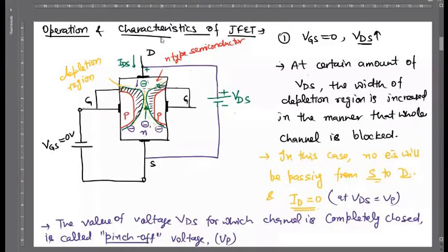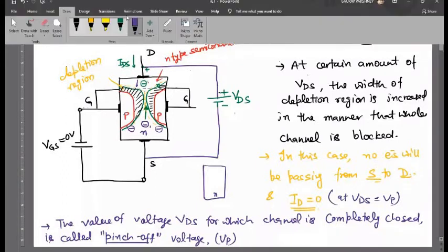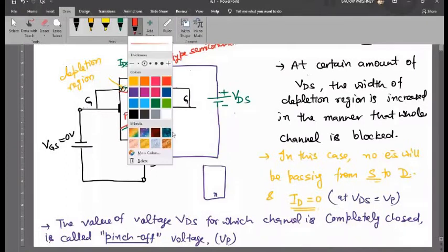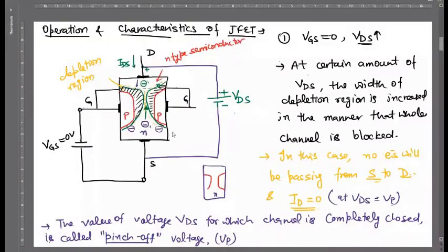This is fully N. Try to understand this. This is N channel slab. This is N slab, full N-type semiconductor. We made two diffusions. Here we made two P-type diffusions in this N-type material. This is heavy doping. This portion starts behaving as P-type semiconductor. This portion remains of N-type, and two P-type diffusions are there only. Understood my point? And this region, the N-type region, behaves as channel.